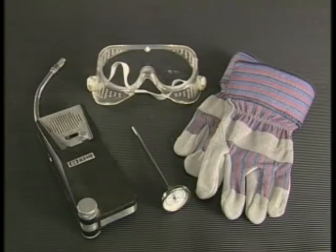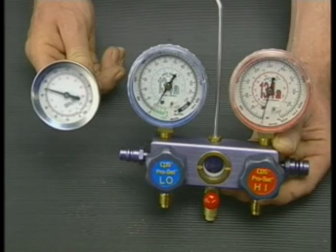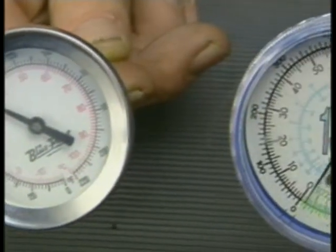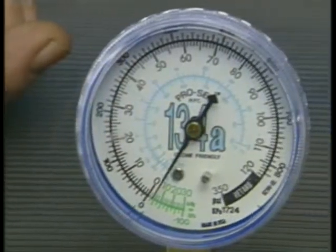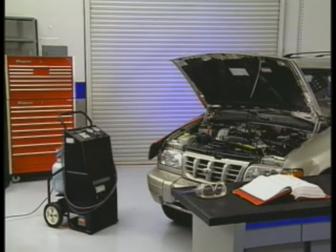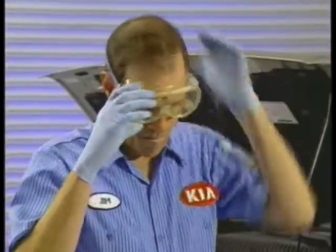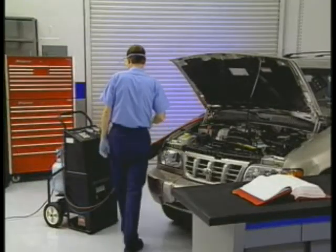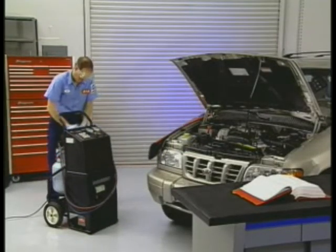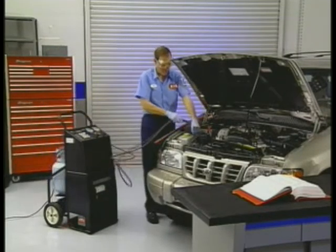The operation of the air conditioning system is dependent on the principles of pressure and temperature. To troubleshoot problems with the refrigerant system, then, is to use the right tools to measure both temperature and pressure. When servicing automotive air conditioning systems, it is imperative to follow all of the safety precautions in the manufacturer's service manuals. Always wear safety glasses when working around systems under pressure to avoid the possibility of eye injury. And always wear gloves, as components can be hot. Additionally, refrigerant contact with the skin can cause frostbite.